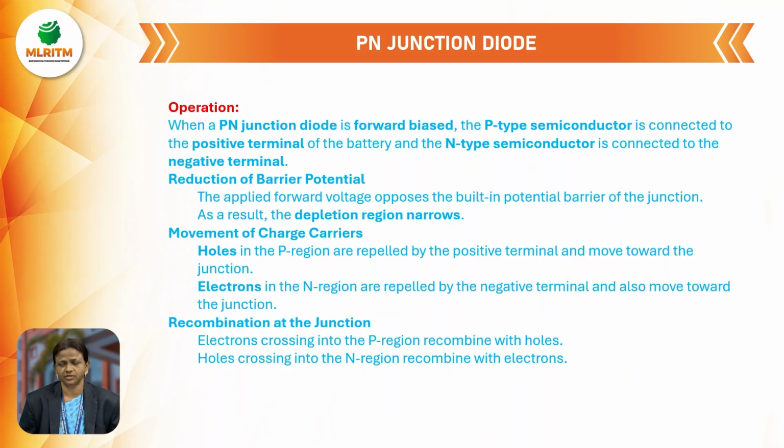Suppose this semiconductor material is doped with a pentavalent atom, then silicon valence electrons are 4, phosphorus valence electrons are 5. So by using 4 valence electrons, 4 covalent bonds are formed. What about the fifth electron? Phosphorus contains another fifth electron. This fifth electron is in a position to donate this free electron to a neighbor atom. That's why n-type materials are known as donors.